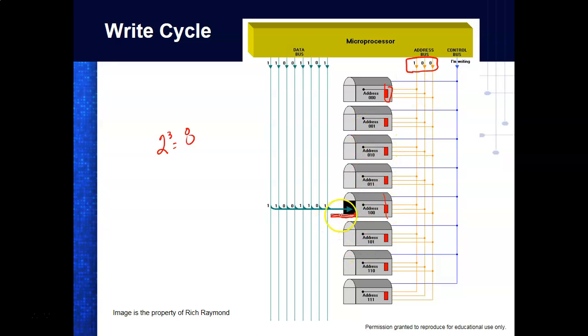So the address bus allows us to access what we call a port. Then what happens is we have to tell the mailbox what we're doing. So here I come up here and I have a control line that says I'm writing. So this tells the mailbox to take whatever's on the data bus and store it into the mailbox. And then it outputs another address and that door closes. It's real fast. So that would be what we call a write cycle.